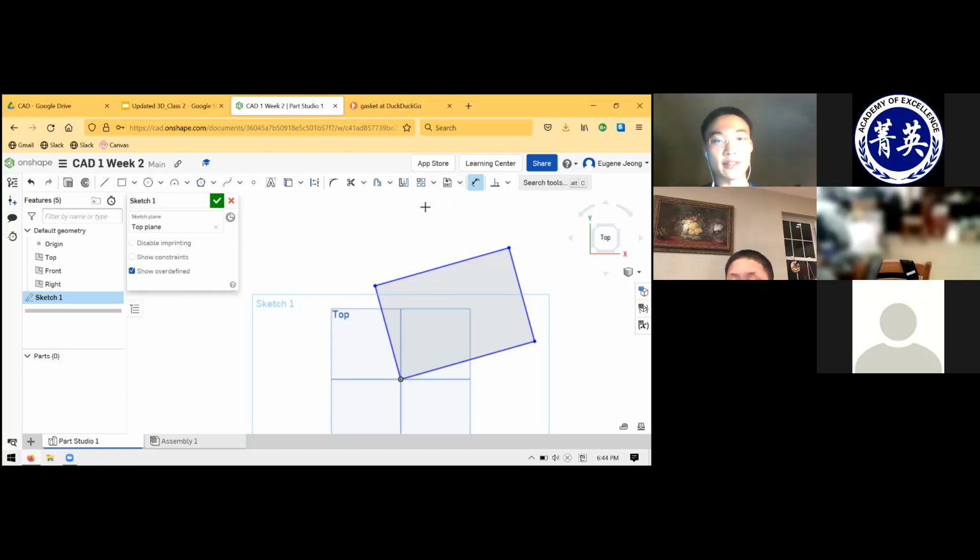So you may have guessed at this point, the purpose of the dimension tool is to apply a dimension, which just means a length, like 1 inch, something like that. So I'll show you what it does. Just like the other relations, I apply this tool just by clicking on the thing that I want to put this new rule onto. And I click again. And when it does that, it selects this text box for me. And here I can just type in any number I want.